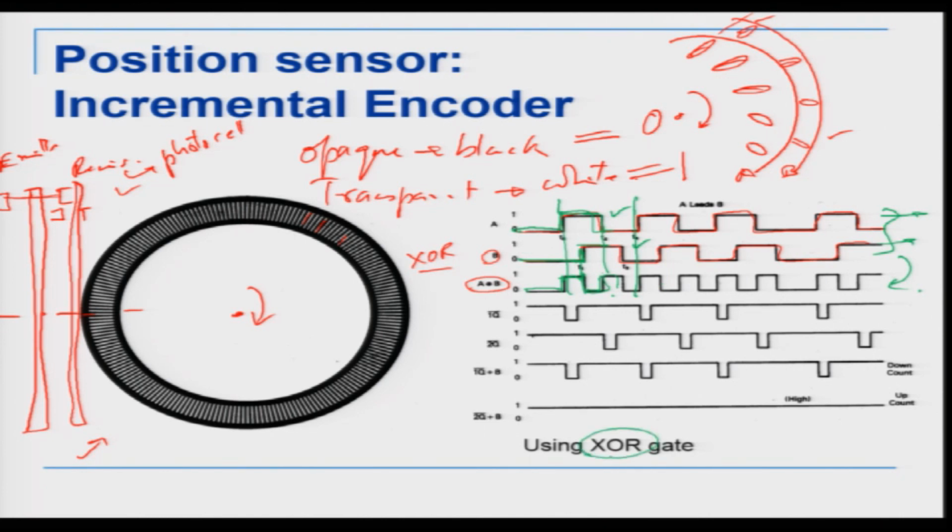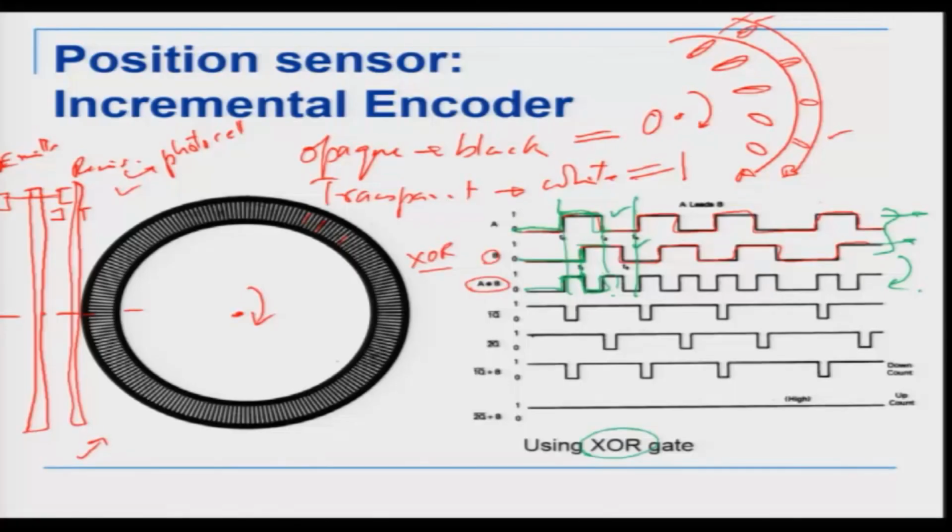This is very simple, and in 99% of our position measuring devices, we are using encoders. So, there will be a motor and there will be an encoder sitting at the back for measuring the position. Now, this encoder is giving us the position theta. If you take the difference between two positions, say theta minus theta dash, you are getting del theta, which is your theta dot or velocity. And if you differentiate this again, then you are getting theta double dot. So, using the encoder we can also get velocity, we can also get acceleration.